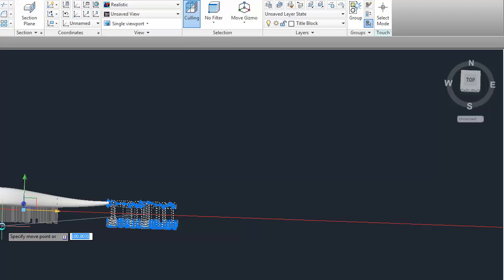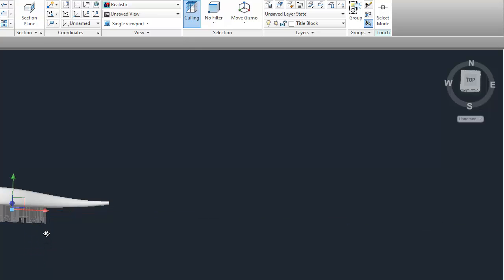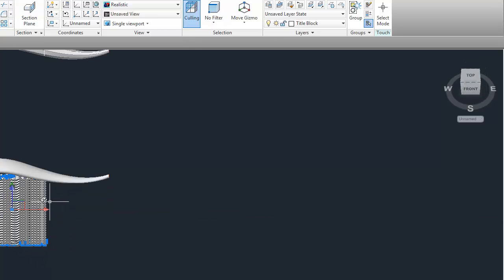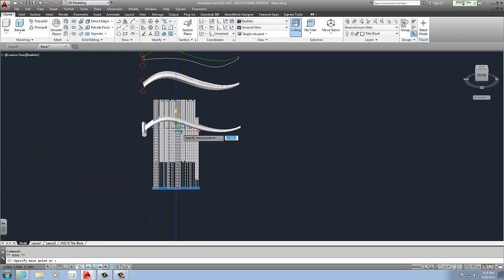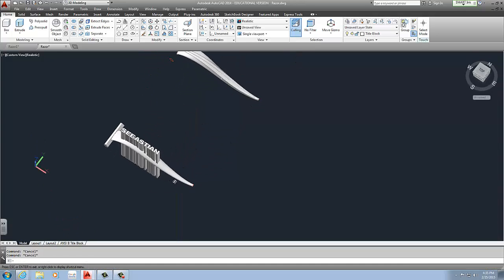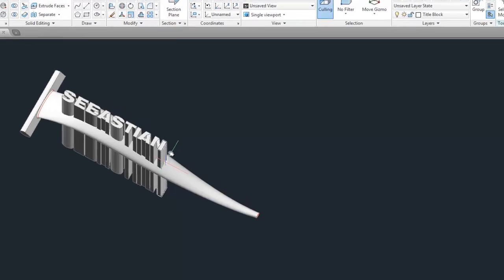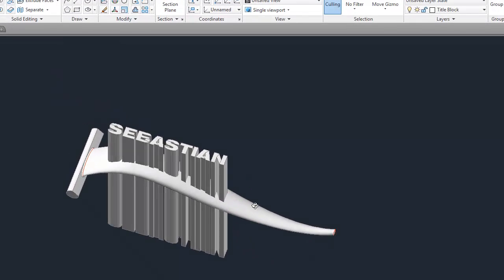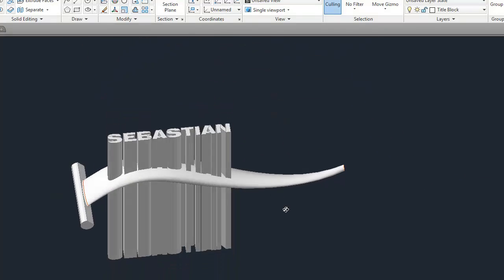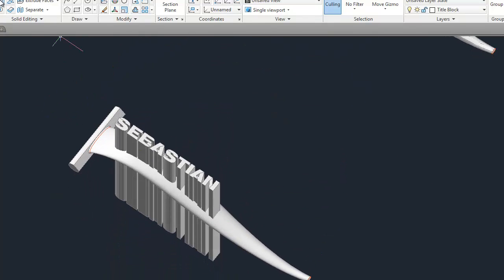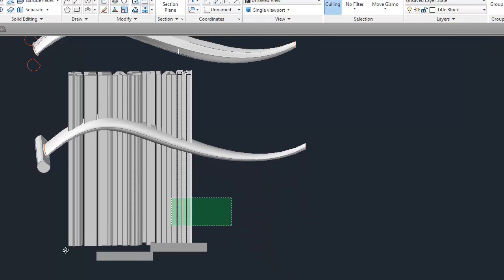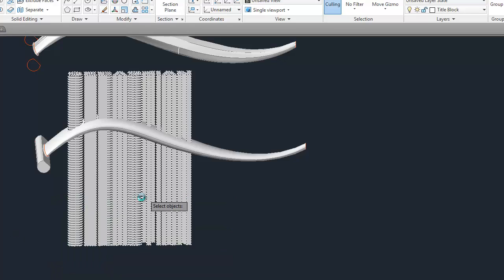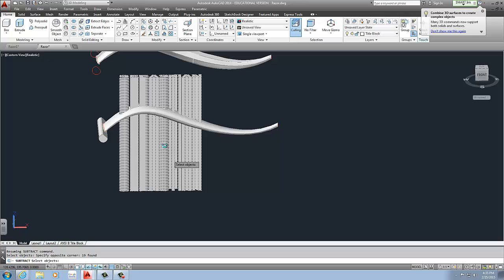Now my computer is a little slow here, so be careful when you guys do this, or save your work before you decide to remove a text from your razor. Once we have it placed at the bottom here, we're going to move it back up across so it fully goes through the actual part that I'm subtracting from. So I'm happy with the positioning. I think this is right, and I'm going to move forward with just subtracting the part. I use the subtract command, I select the razor hand, and then I select the razor the text I'm removing, and I click enter or space.